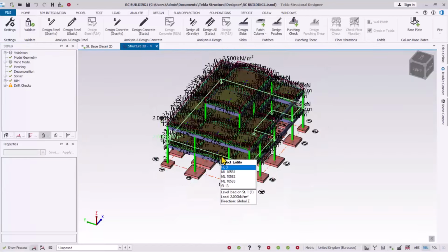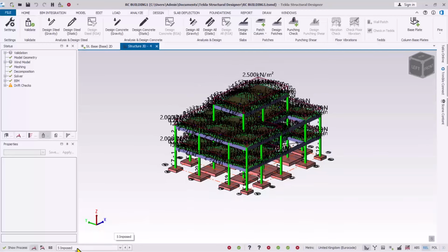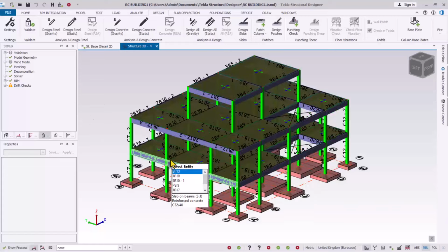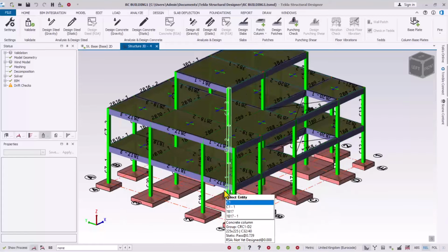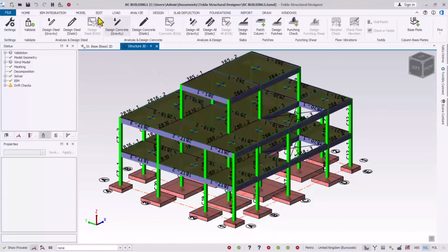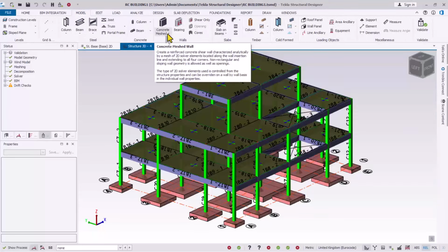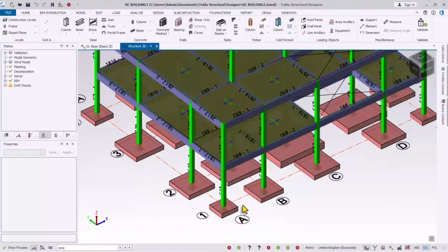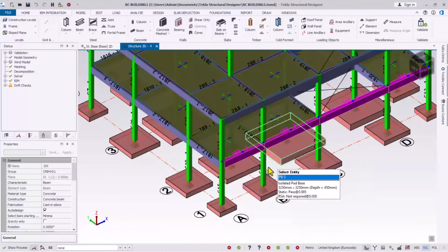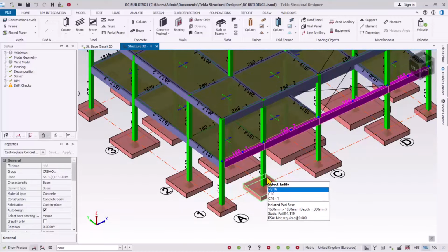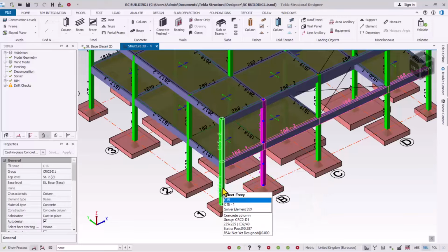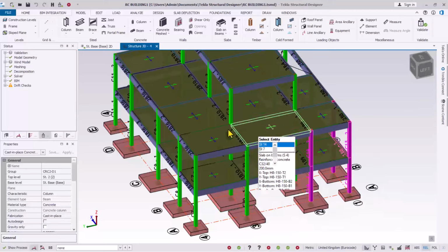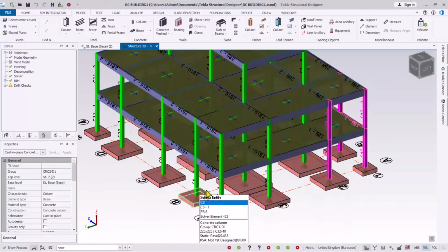So in the structural view, you have this. Because the load is active, I will choose unknown right here to have none of the load active. Now I want to modify this structure by applying these options of a concrete mesh right here, this one. So to modify this structure now, I will have to delete some of these beams. I have that selected. I'll hold the control key so I can select these columns on this one. Okay, so the same thing I will do at the 4 edges of this building model.